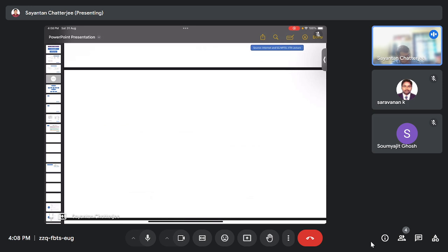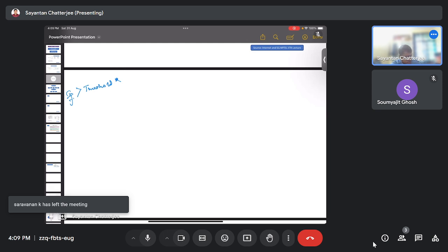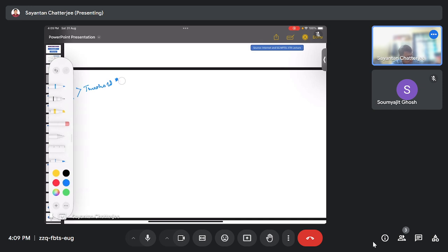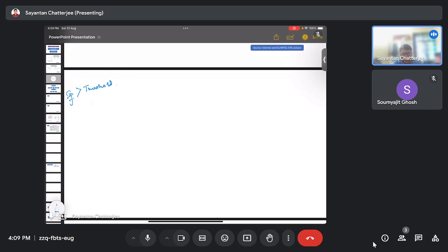So for relays, as we all know, we have some set point values, based on which we have a threshold. If this threshold is crossed by the sensed current, that is, crossed by the fault current, then the relay would send a command to the circuit breaker, and the circuit breaker would trip that faulty location, right? And that too within a prescribed time frame.